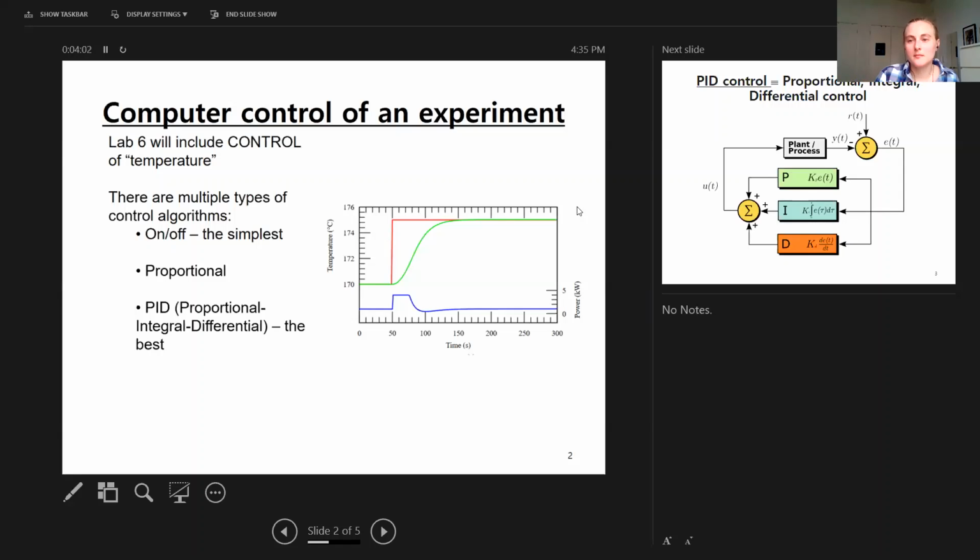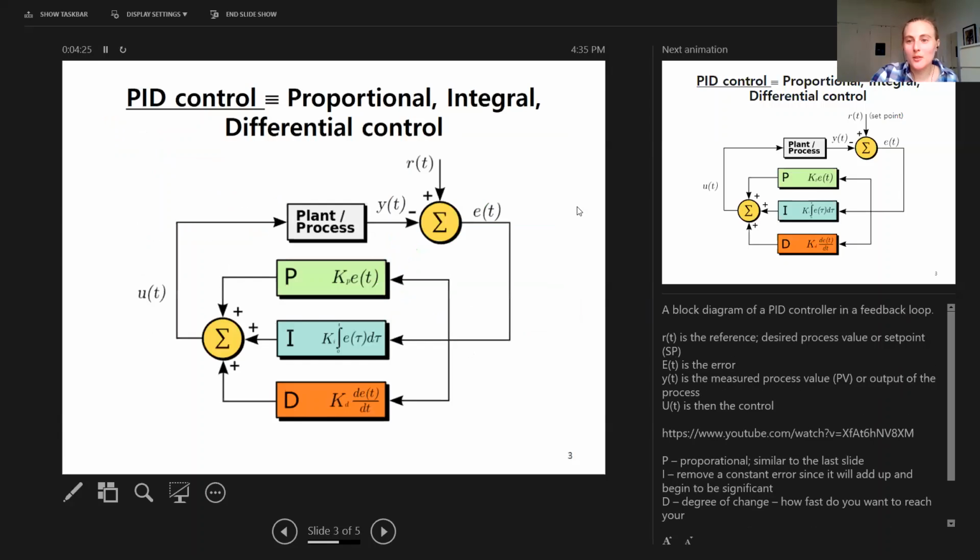The biggest one that we dealt with was recurring oscillations, so that stuff would overshoot and then come back down and undershoot, and then you got stuck in this oscillation pattern. But then we changed a bunch of the integration controls so that it slowed down, and a lot of the differential controls so that it would stop doing that. But yeah, it's really nice. Yeah. So that's what you'll be walking through tomorrow.